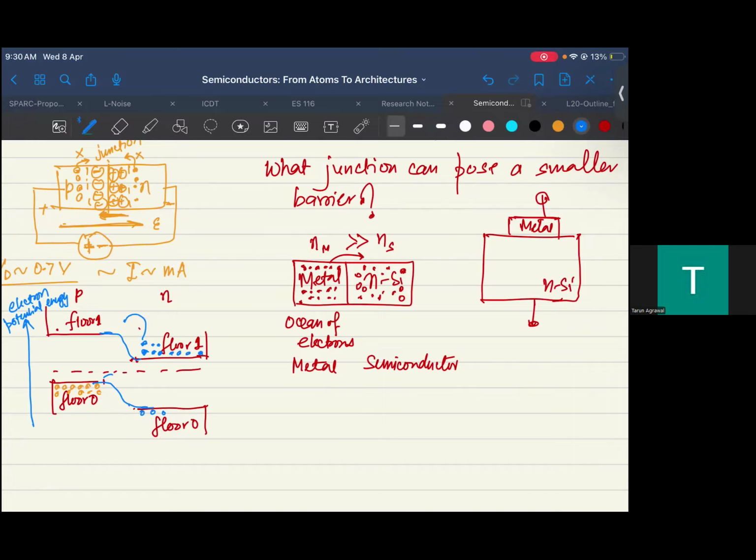And that is what you see now: for the holes, the potential energy would be in the opposite direction, because it's the opposite charge of the electron. So that means for holes also there is a barrier. So this is what we know as the electron barrier, and this is the hole barrier. And you see this in this diagram also. This is the electric field, which is what we were seeing, right? This barrier is posing this internal electric field, which is coming from these two, the electron barrier and the hole barrier. That is exactly what it means.